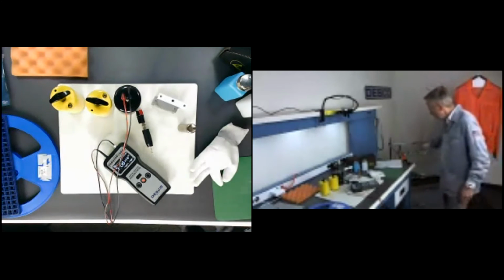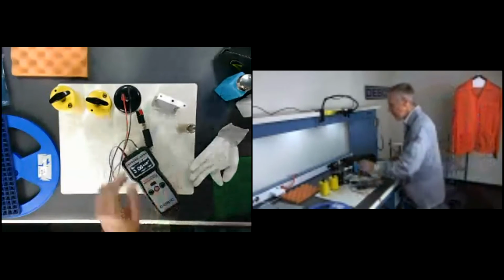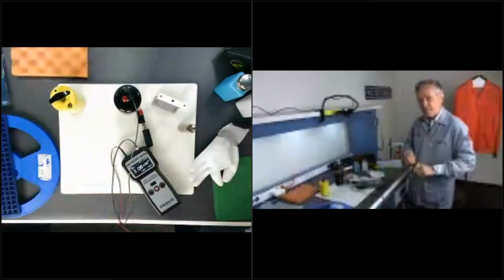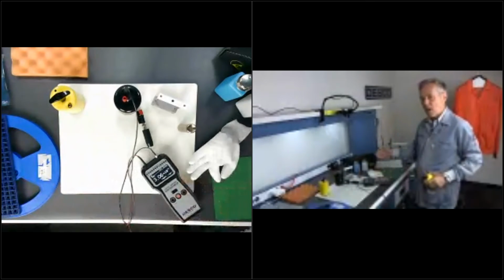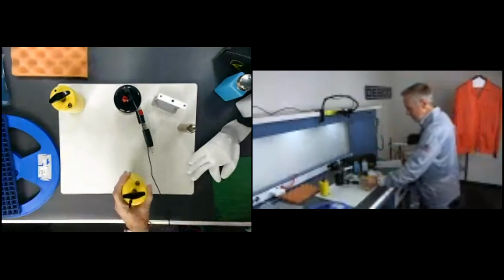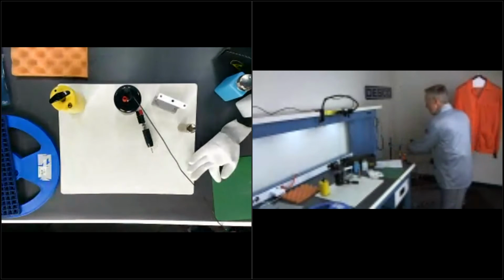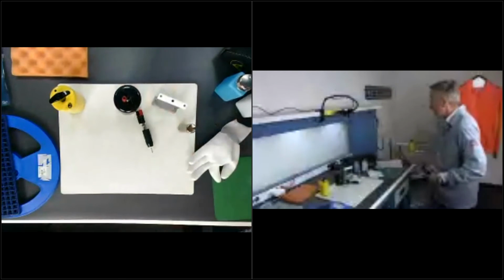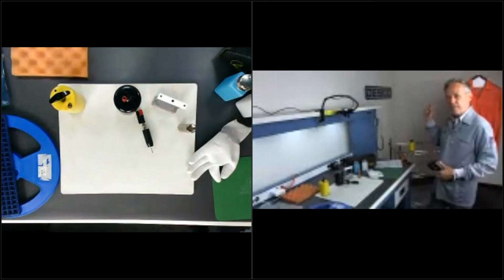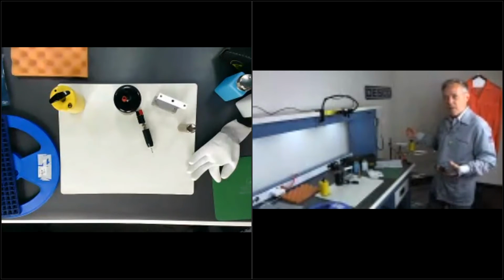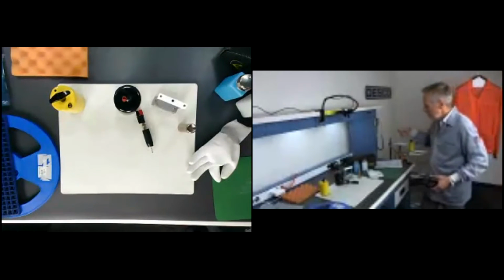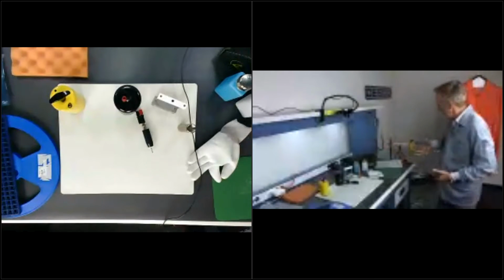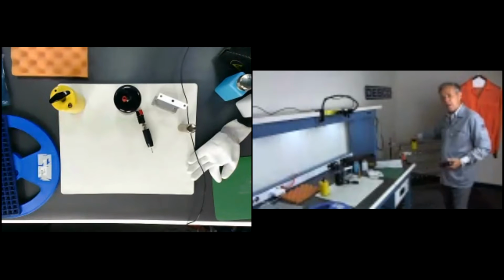So as far as when we're measuring things like a cart or the floor itself, again, for compliance verification, the mandatory test requirements are resistance to ground. I can show you how to do the RTT, but the mandatory requirement is resistance to ground. So my floor here is grounded back to an AC outlet on the other side of the room. But your AC ground is basically universal within your environment. So I'm going to plug my other test lead into the same ground point that I did my mat ground. And I set my 5-pound weight up on top of the cart.